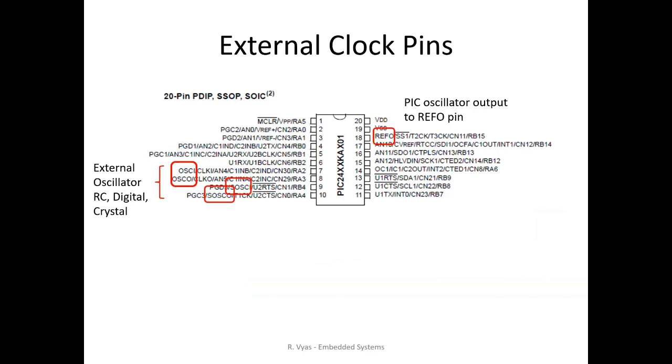So you have the option of configuring external clocks if you're using a crystal oscillator. You have the option of connecting it on the primary external I/O pin or the secondary oscillator pins, which are pins 7 to 10. But in our case, we are not using this. We are using the internal RC clock. But just for reference, if you want to use an internal crystal oscillator or an external oscillator, you can apply them here.